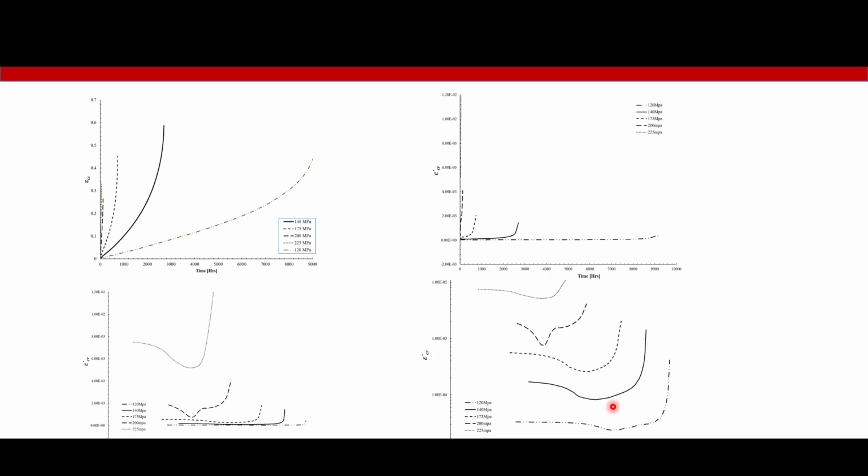So this is a mistake which people make, also in modeling creep and creep crack: they assume Norton's law, which has no time dependence. So you only think that if I can model secondary stage creep very simply using Norton's law, then that will be it. But that will not be simulating the real material's behavior.